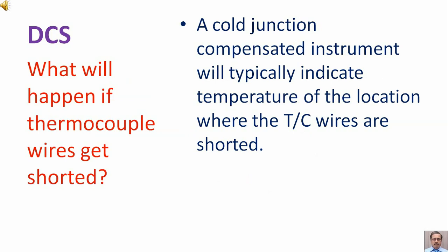What will happen if thermocouple wires get shorted? A cold junction compensated instrument will typically indicate temperature of the location where the thermocouple wires are shorted.